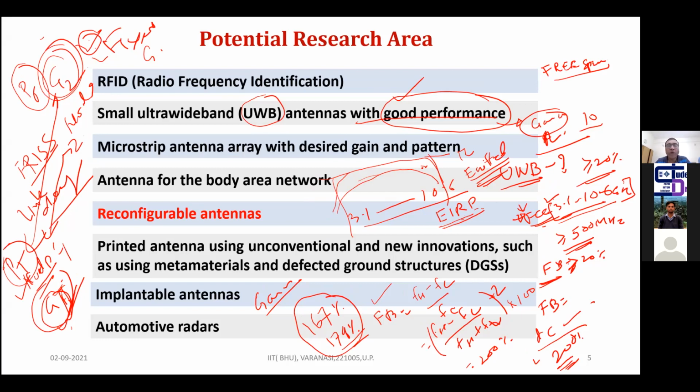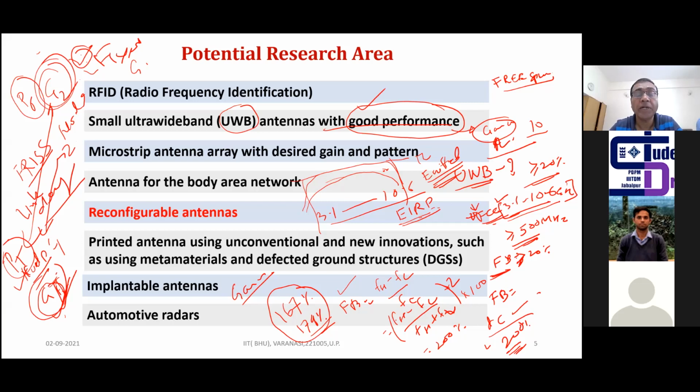Always, what we are doing is considering antenna performance in the free space environment, either in simulations or in measurement. We perform the measurement in the anechoic chamber, where we are artificially creating the free space environment. And the simulations ideally consider no losses. So we are considering the free space environment in both cases. But practically, this is not the case. Practically, we have the scattering environment, so we consider the multipath environment. We have reflections, refractions, and scattering.